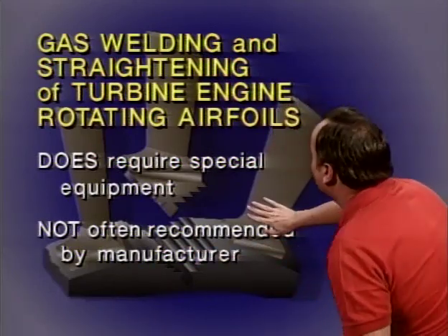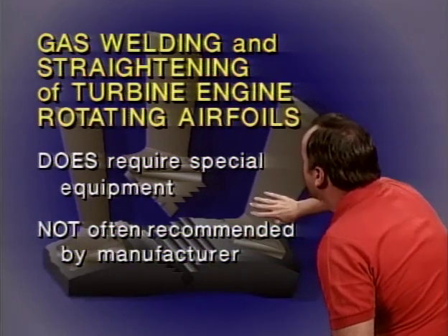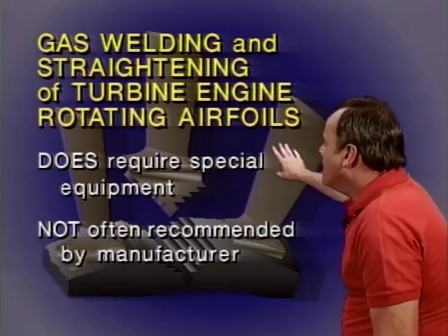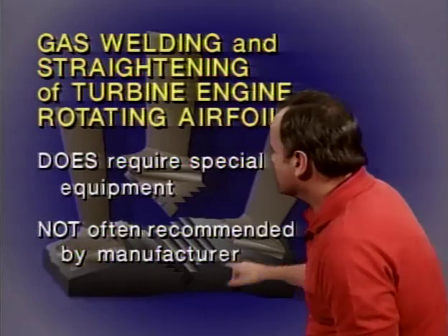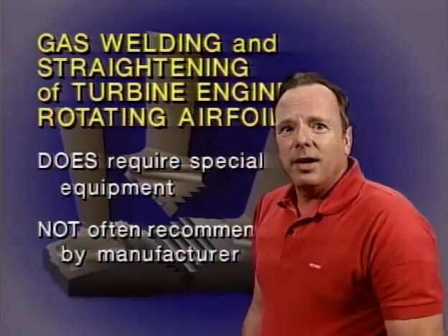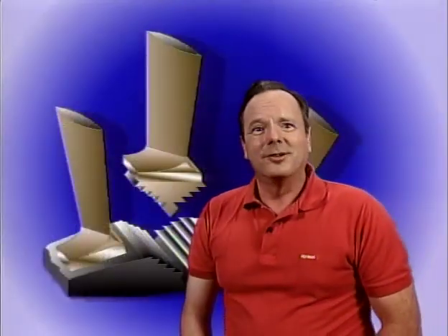So don't plan on doing a field welding or straightening of a turbine blade, because it requires special equipment and it is not often recommended by the manufacturer. Fat chance, I think they're trying to tell you right there.